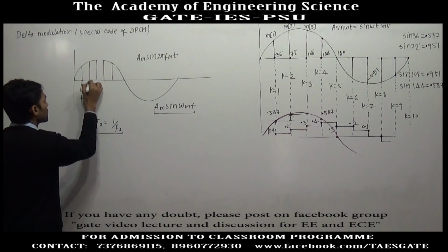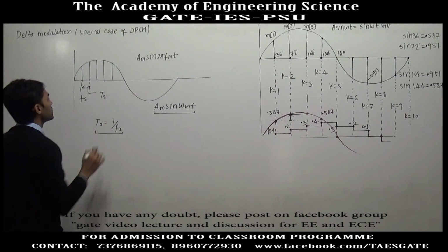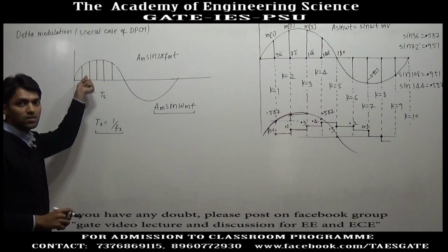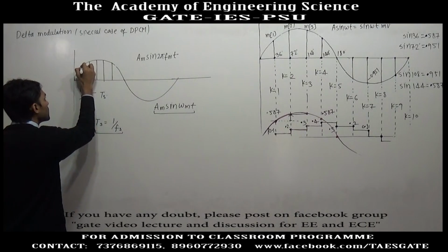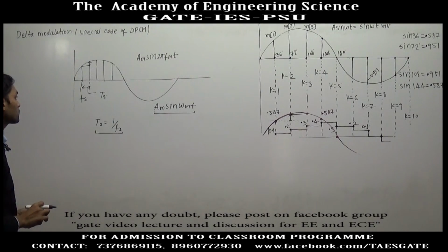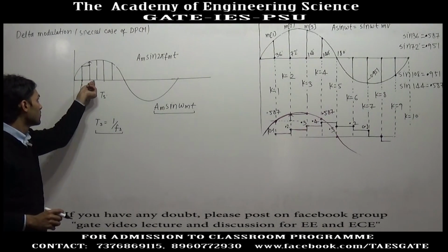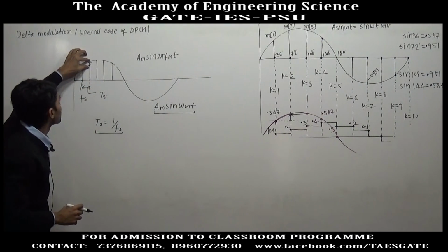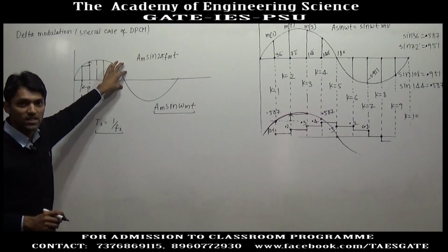If the frequency is Fs, these two intervals will be Ts. So, if we increase the frequency, the interval between the consecutive inputs to the delta modulator will be lesser. If this interval is lesser, the difference between the consecutive inputs will be lesser. Now, whatever is the value of the interval, it will always be fixed. So, if the x axis is fixed, the maximum change in the consecutive output will occur at the same point where the graph has maximum slope.